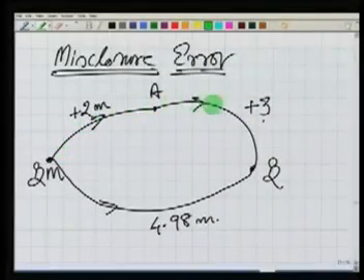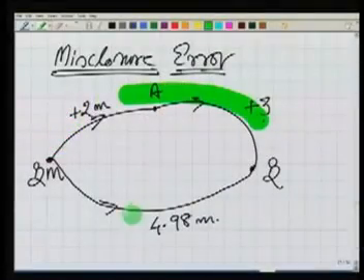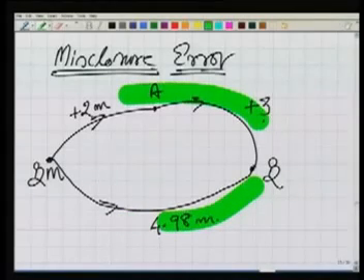What does it indicate? While taking the observations from two routes, one route here, this plus this, I found the RL of this point. Then the second time I am doing it directly here, I am finding the RL of this point. The RL in both cases is coming different. Is it possible? On the ground it is a single point. It should have one RL, but we are getting two different values, through this route and through this route. It's not possible.